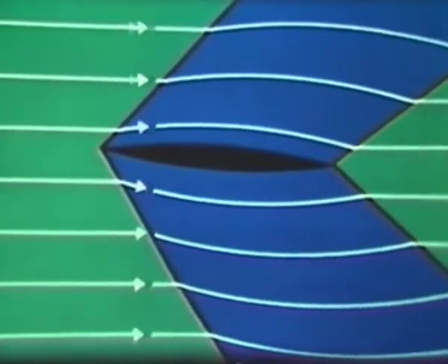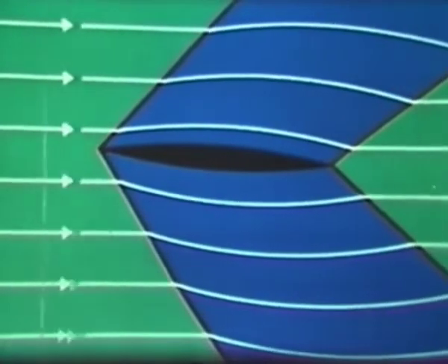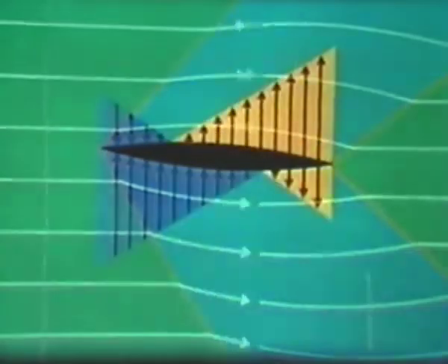Two arcs of circles go to make another possible section, the biconvex aerofoil. The thickness here is again exaggerated. After passing through the shock wave at the leading edge, the air speeds up gradually around upper and lower surfaces, and the pressure is reduced on both. Here's the pressure distribution. This area represents lift, which again acts at mid-chord. Here's a Schlieren wind tunnel picture.